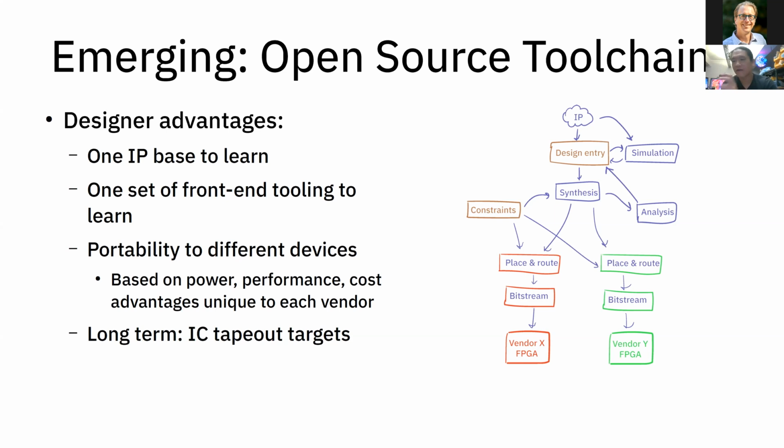So some FPGA hardware families have really low leakage power, and some have specific DSP blocks built in that you may want to leverage. It'd be really nice to be able to say, okay, vendor A may have an FPGA that we can target with exactly the same code base, and then we can go to vendor B, and if we want a higher performance version but are willing to burn the power, that's just a swap of the hardware and not actually have to rewrite any of the code.